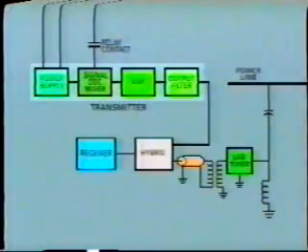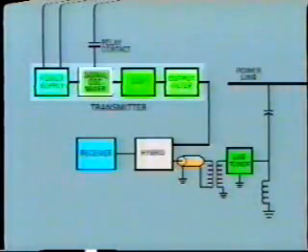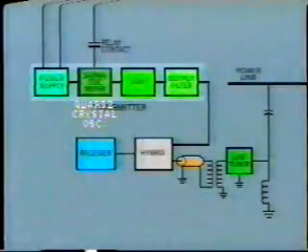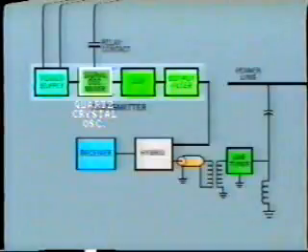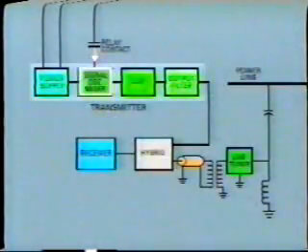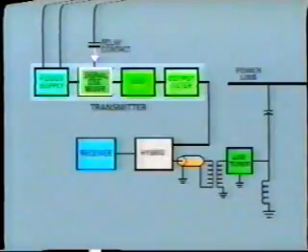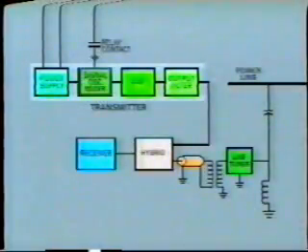Let's look now at the transmitter. The initial signal is produced in the oscillator mixer at precisely the desired frequency. Generally, quartz crystal oscillators are used, and these are quite easy to replace in case of a defect. This circuit is controlled by the incoming signal from the protective relaying scheme. This may switch the unit on, or in the case of FSK, switch frequencies.